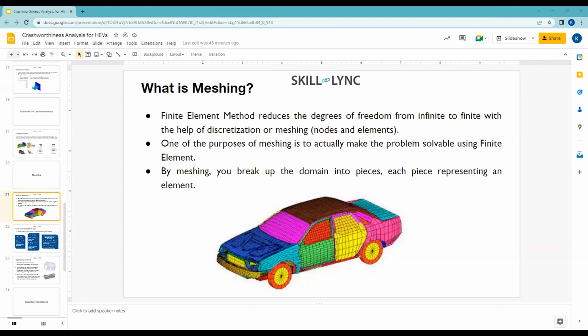Traditionally, in the case of normal stresses, suppose you have this 1D beam and you are applying a force like this. By Hooke's law, which is a traditional law we use, stress is directly proportional to strain up to the elastic limit, or stress is equal to Young's modulus times the strain. Stress was your force per unit area.